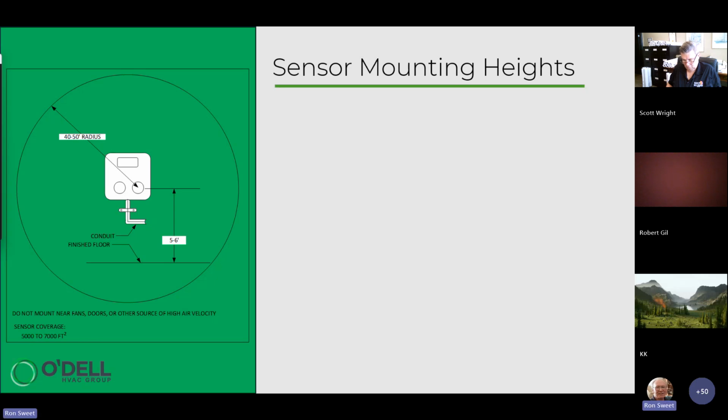So we don't have all the false alarms that plagued the industry way back when they were first introduced. And mommy and daddy were freaking out and unplugging the thing and pulling the batteries out because mommy burnt the toast or daddy was boiling water. Today's residential carbon monoxide alarms have to see 90 ppm for 45 minutes before they start emitting an audible visual signal.